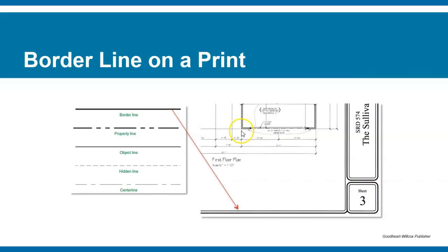Notice as the extension line gets really close to the object that it's pointing to, it doesn't actually touch. You see this little tiny space in there? I have some drawings where the lines get very close, and that's architecturally not correct because it can be confusing. An extension line extends very close to your object line, but it doesn't actually touch.